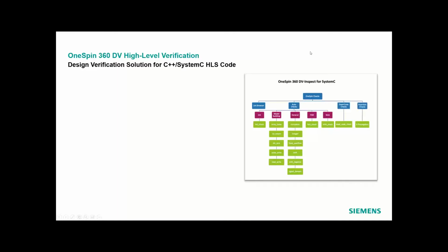So let's go deeper into the first solution that I mentioned: DVInspect, or auto checks, that are automatically generated once the SystemC design is imported into the tool.